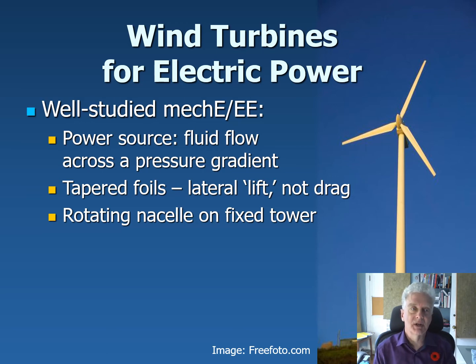This is a pretty well-studied mechanical and electrical engineering challenge. The power source is fluid flow across a pressure gradient, so in a way it's very much like the other kind of turbines you will have studied in your course, things like hydraulic turbines running from the pressure gradient of water over a hydraulic dam, and also from steam and air pressure turbines. So this one works that the blades are tapered foils, so they have a profile that changes through the length of the shaft. And they're creating lateral lift. They're not working by drag. So this isn't like a pinwheel where the wind blows on it and just simply pushes it along.